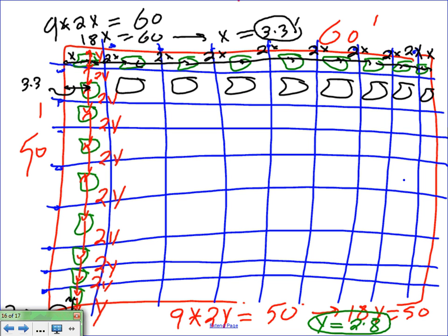We can't install open incandescent lamps, guys, pendant lamps, and open lamps that don't have a globe over them. You can't install them in a closet. The picture I showed you guys, please review it. What type of fixture you can install in a closed closet, and that closed closet could be in your basement or your house, or it could be here at Dunwoody. It doesn't have to be, as long as it's dedicated for clothes.